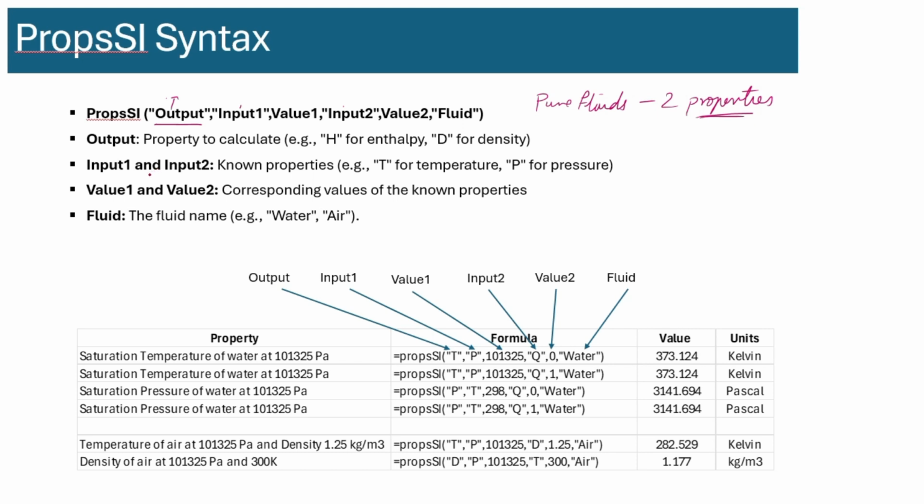So in this case, if you input pressure and quality, for example, and we'll get to quality later on, it's going to tell you about the temperature. Okay, so typically you need two inputs, and then you need to put in the actual value of the inputs, and then you have to tell the CoolProp what is the name of that fluid.